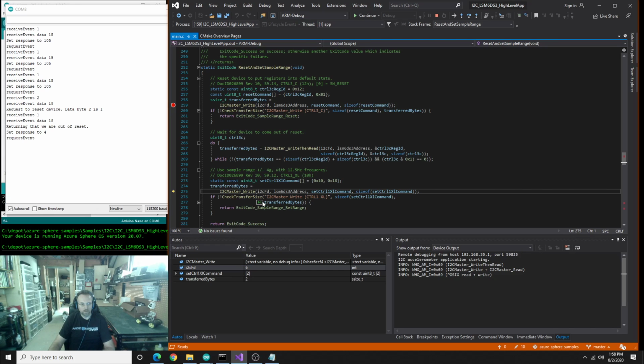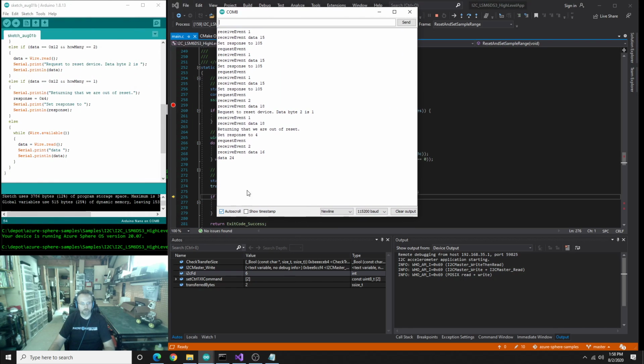So cool. Now let's look here. Great. We are writing out 10, which is 16, and then a second byte, which is this 18 hex or 24. And you can see that we didn't have a handler for this 16 or 10 hex.